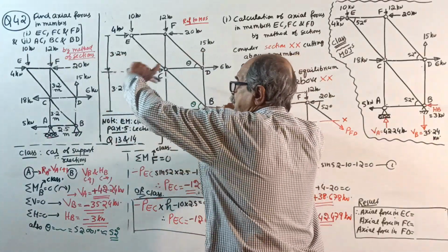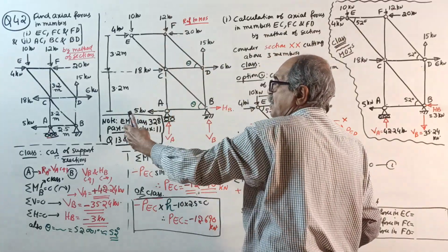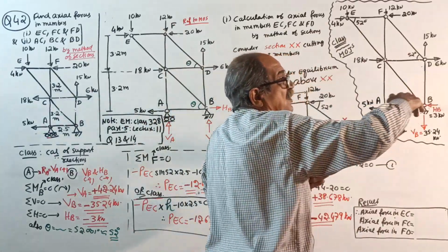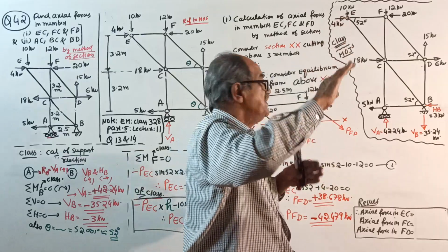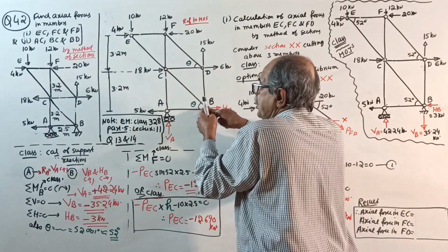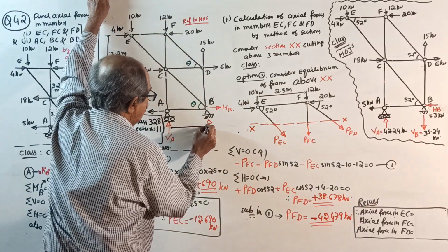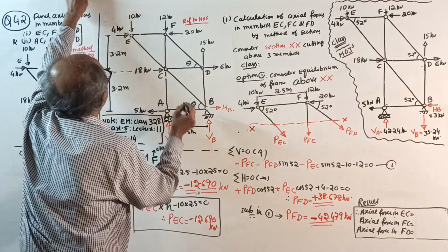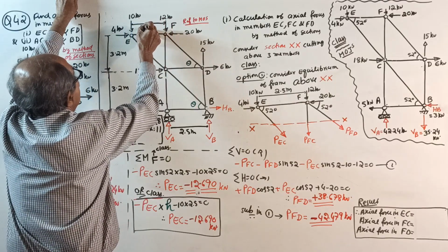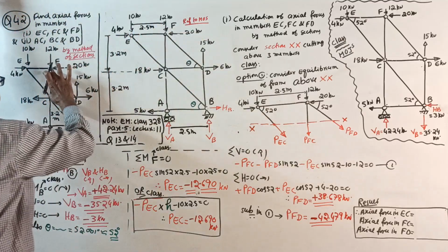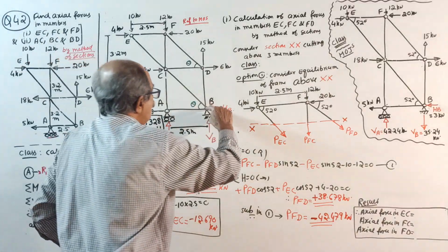Okay. Clockwise positive. VA, see, again I am telling, vertical load into horizontal distance, horizontal load into vertical distance. If inclined load is there, if you don't resolve, perpendicular distance. Okay, start. Moment about this point. Finger should be here. VA, I forgot to write something here. See, you have to write this dimension. How much is it? This is 2.5 meter. I forgot, right? 2.5 meter. Here also, there is no place to write. This also is 2.5 meter. Height is given here, 3.2. This also 3.2. Okay, now, take moment about B.